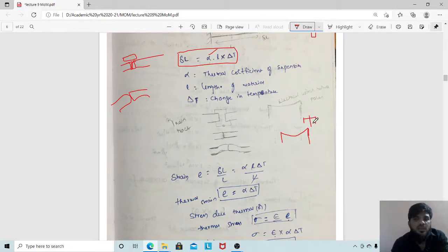When they break, because these are live wires, someone may be hurt when the live wire falls down. Similarly, if you make it hang too much, it can even touch the ground. So to avoid that, they give only a small curvature, so that in winter it is able to contract. In electric wires the provision is given for contraction; in railway tracks the provision is given for expansion. Clear? So this is thermal stress.